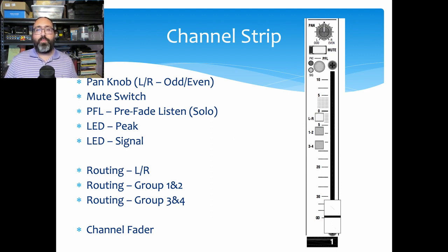Right underneath it is the mute switch. Now on this Allen and Heath, it is a mute switch. There are some consoles, particularly Yamaha's, where instead of it being a mute switch, it's an on button. So it has thrown many an engineer who has come from one modality and has to jump into another as to which one it is.